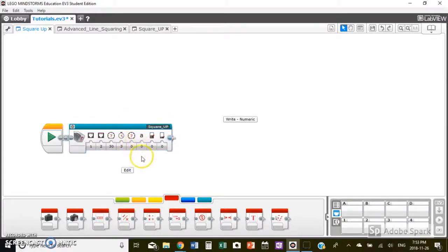Normal speed is 0, KP at, I think, 0.5 should do the trick. Average for my bot is 35. Low is 8 for my settings. Now let's download the program and let it run.